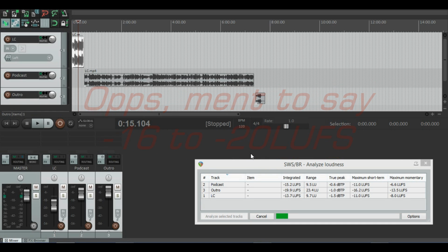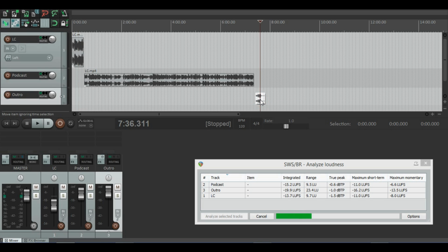Now, as it does this, I want to show you, you will hear people talk about their background noise, and that is totally different from your noise floor. What your noise floor is, everything electronic has background noise in it. Okay? It's just the way that it is. It's the nature of our universe.